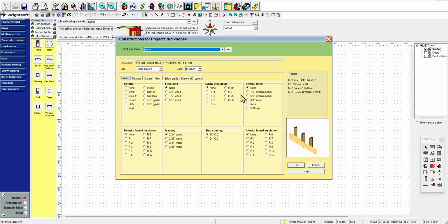Let's build a wall. Actually, I'm not going to go with the block wall. I'll go with the typical frame wall. In Arizona, it's very common. Even though we had that picture of the home, it definitely wasn't stucco. It was some kind of siding, like a vinyl siding. Sheathing, we'll say that it's got a 3/8 of an inch thick wood sheathing. That's typical. We'll say R13.